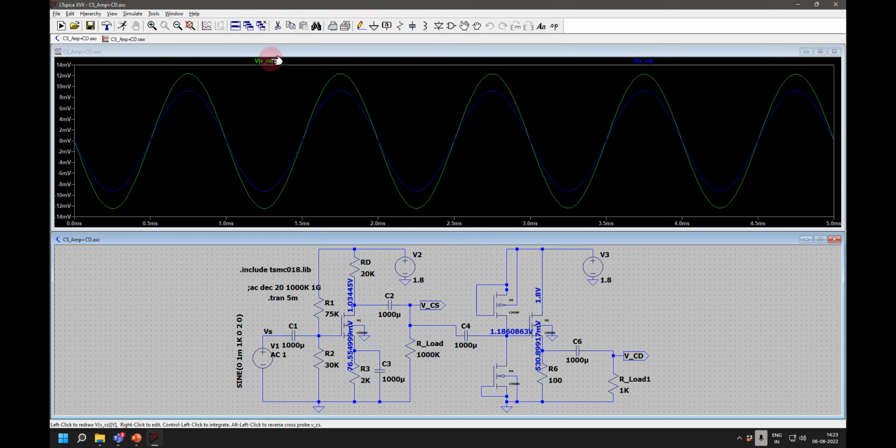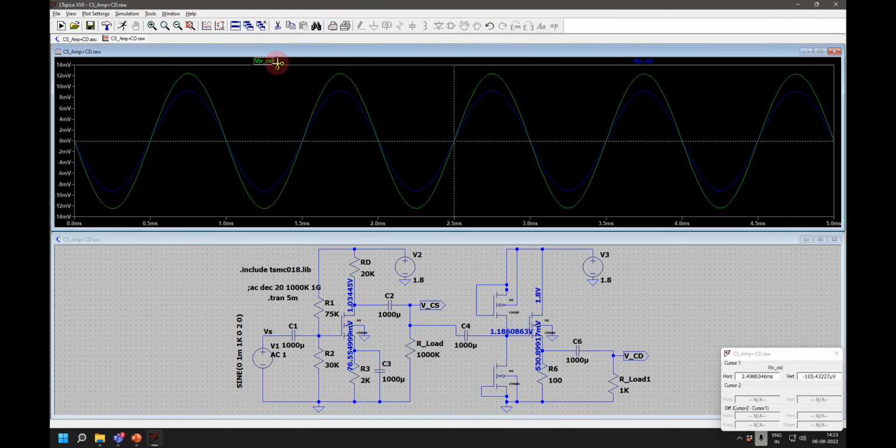This will always be in the picoampere range, right? The gate current, yeah. So the current gain will be very high, 10 to the power 7 or 8. Yeah, it can be very high. Do we use this current gain anywhere? No, we generally use this for boosting up the voltage, giving a high input here.